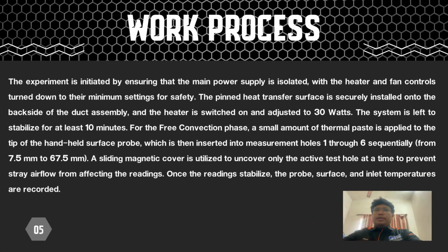Work process. At the beginning of the experiment, the main power supply was isolated and both the heater and fan controls were set to minimum for safety purposes. The pin heat transfer surface was installed securely and the heater power was adjusted to 30 watts. The system was allowed to stabilize for around 10 minutes.